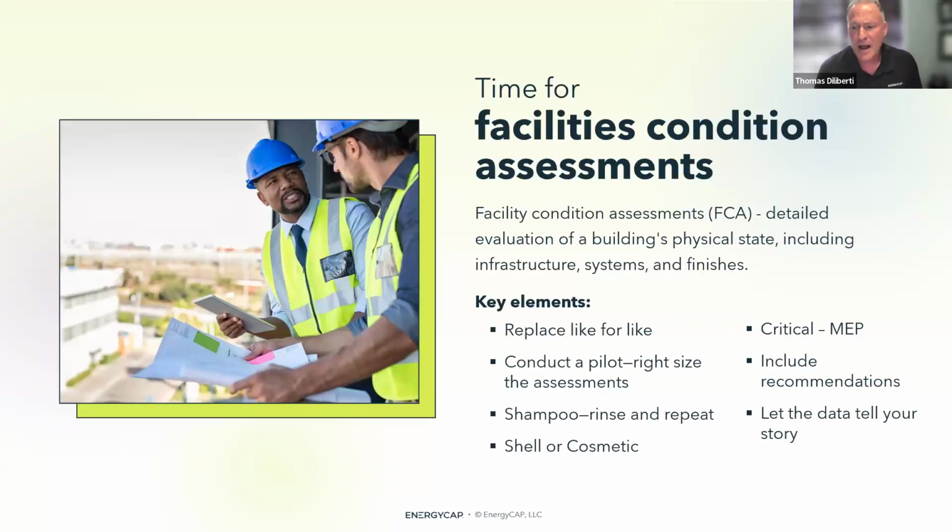So as you're going through this long process of building improvements, at some stage you have to consider facility condition assessments. And I just want to talk about these a little bit. So there are many companies out there that do these for you. And usually they work under the structure that they're considering pieces of equipment in the facilities that are aged and ready for replacement. And what they look at is replacing like for like. So if it's a heat pump building, you're going to keep it a heat pump building. You're just replacing the old heat pumps with new heat pumps. And so it might be time to reconsider those things.